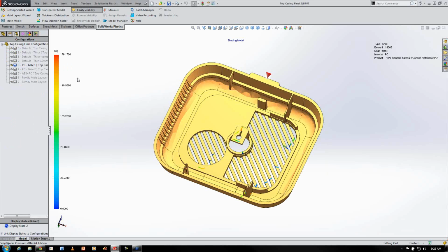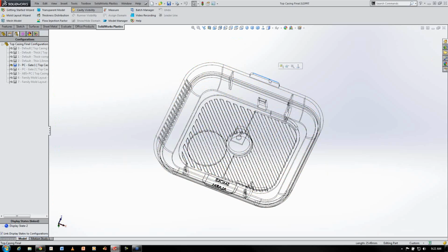So now that we've got the geometry refined, if you will, let's take a look at manipulating some of the parameters just inside of plastics. So maybe the first guess of injecting the part up on this model edge wasn't the best choice. Maybe there are other areas of the part that would fill maybe faster, maybe more complete, and eliminate some of those potential defects.